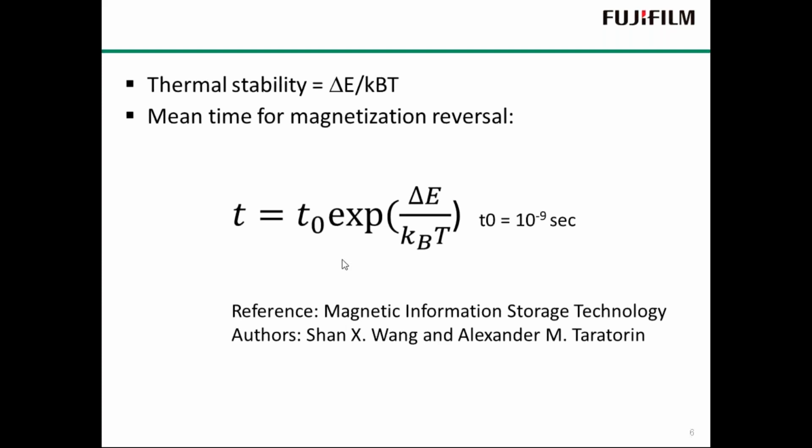That makes sense. So Ed, are you referring to the substrate and the binder separate from the actual particles? Is that what you're trying to differentiate? Yeah, I'm saying that once you magnetize a barium ferrite particle, the magnetic field in that particle doesn't degrade very easily. You could soak the cartridge in water and it would be fine from the magnetic particle point of view. In other words, the field doesn't switch like the superparamagnetic limit of disk is happening now. But that doesn't mean you could take that wet media out and run it on a head and recover the data. You wouldn't be able to read the transitions, or the media would gum up or something like that.